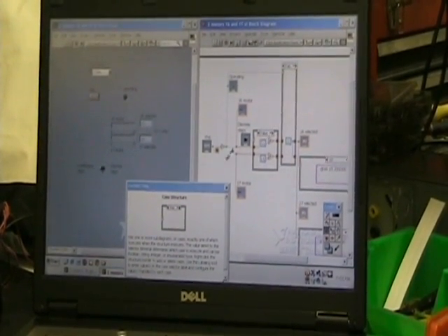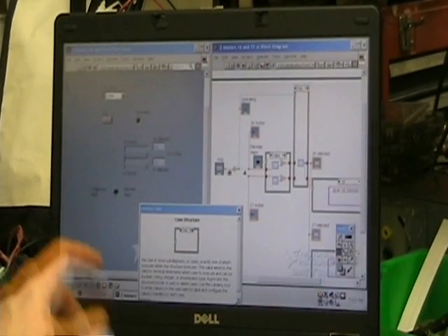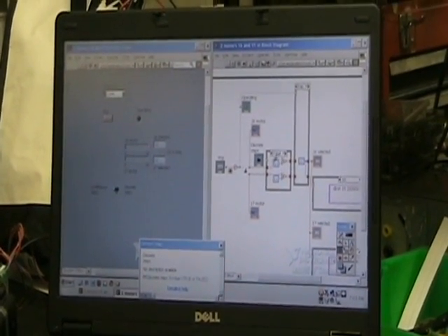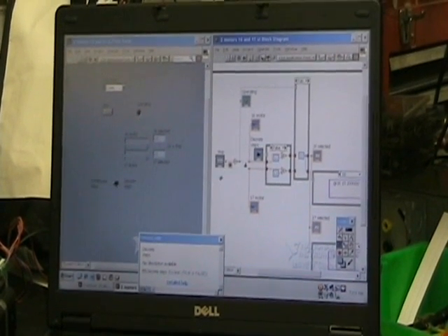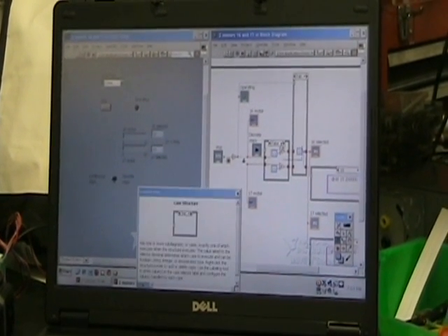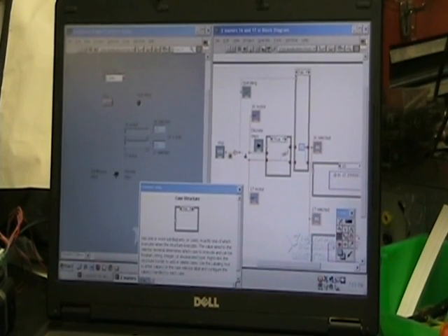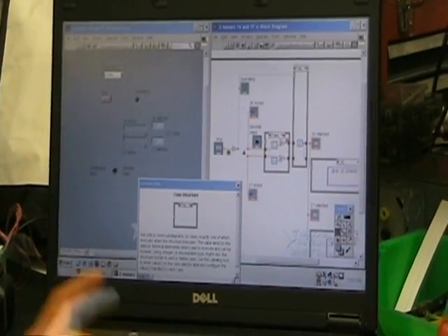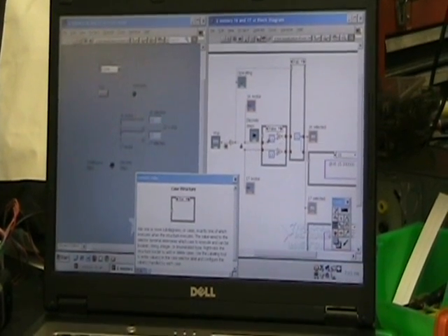And then this over here on the left, the continuous steps or discrete steps, is what feeds this case structure. So if we go to the true command, it'll be straight, see the wires are straight across. But in the false, which is if you select continuous, it adds 11.